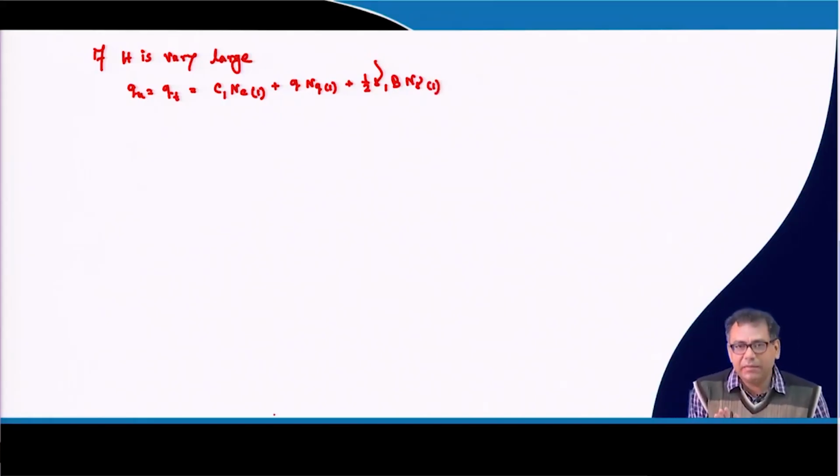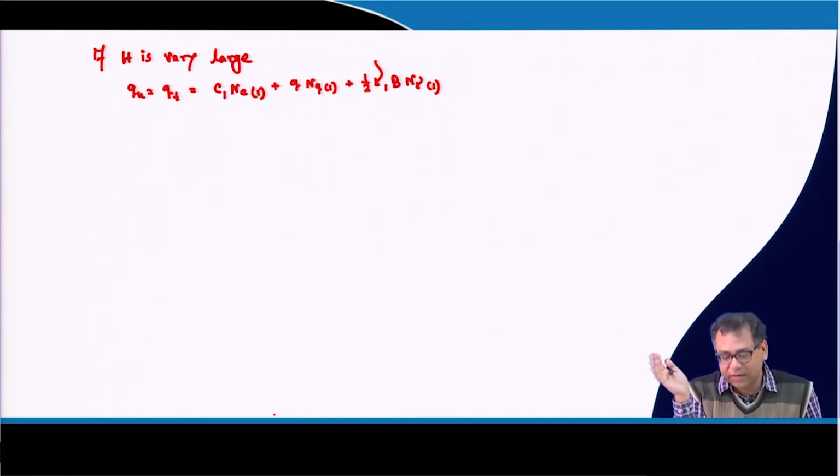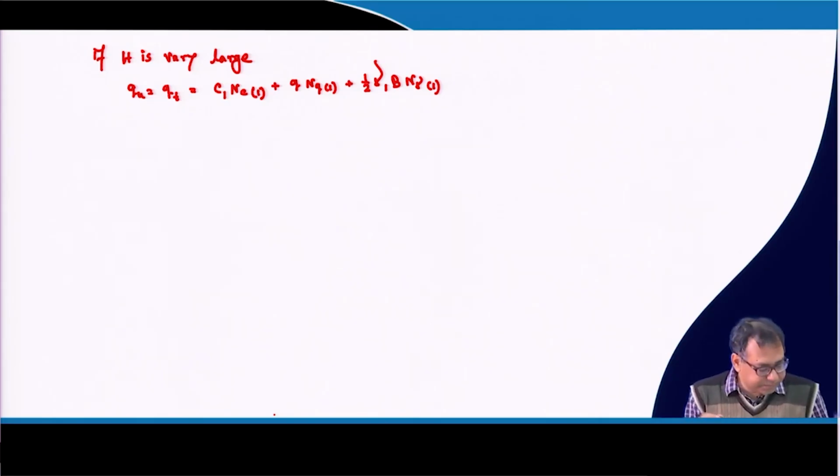Okay. So, here I am not giving other factors or the bearing capacity correction factors, all those things. I am deriving the basic equation with only the coefficients, and we assume that all the other factors are 1 and it is for strip footing. So, that is why this is the equation. This is the bearing capacity if the foundation is resting on the top soil only, where the bottom soil influence is not there. So, that will be the maximum bearing capacity of this foundation.